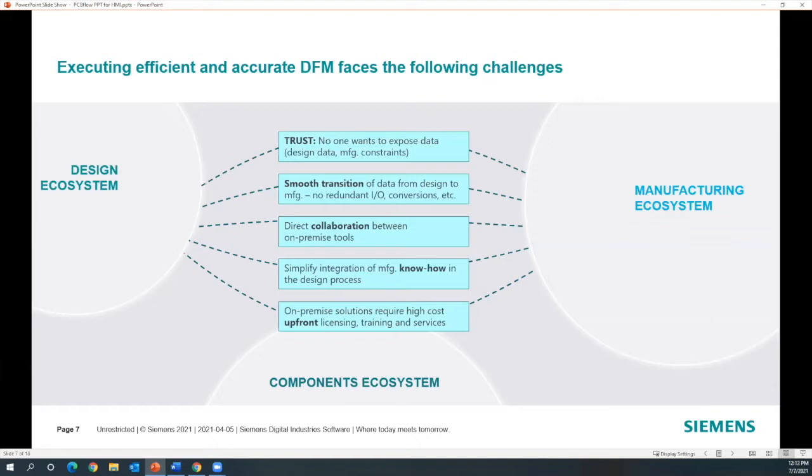It's the actual discrete components that you're going to be placing. So the bill of material, all of the different ICs, capacitors, resistors, everything there. Because we know that in order to do a real DFA, design for assembly, you need very good modeling of the components. One of the issues we have is that designers do a cell. They have an envelope of the CAD package. They don't really care about the distance between the pin and the body, the size of the pin and the type of the pin. But when we go to assemble, we want to make sure that that pin is going to touch the pad at the right place and that the paste is going to be at the right location. We've got to model that.